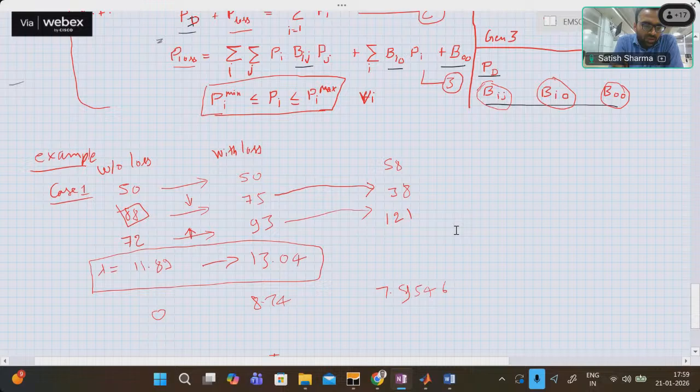In Europe, there are many countries producing more than 50% renewable, and if they do not make them dispatchable, the system operator will face a lot of problems: frequency deviations and voltage deviations as well. It has to keep a lot of resources to supply those variations from the renewable. That's why they are asking renewables to become dispatchable, so whatever you have committed, you should provide.